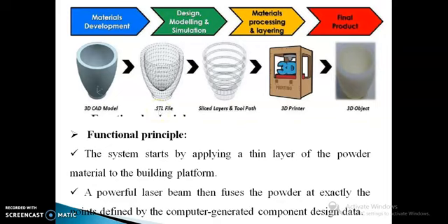The 3D model is generated with the help of a computer, and we have to read the information using the 3D printer or additive manufacturing machine. So we have to convert this CAD model into the STL file. After converting, the STL file is fed to the slicer. What is the main function of a slicer? Not a machine, sorry, slicer software. After feeding it to the slicer software, it will divide your object into slices,